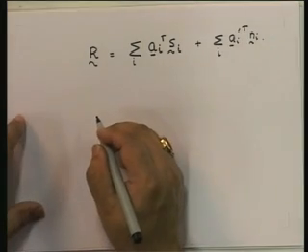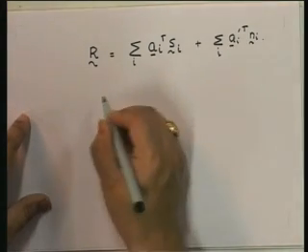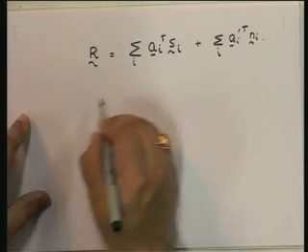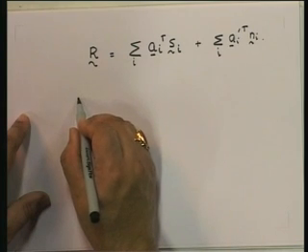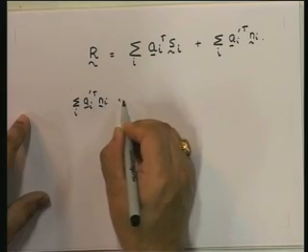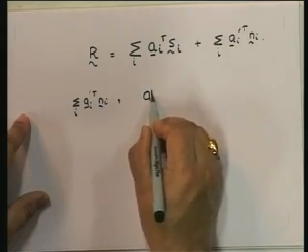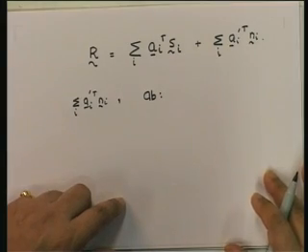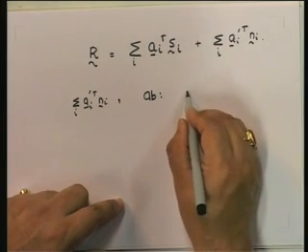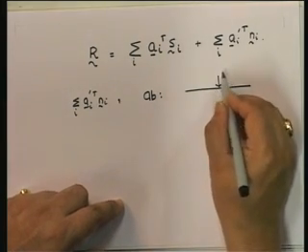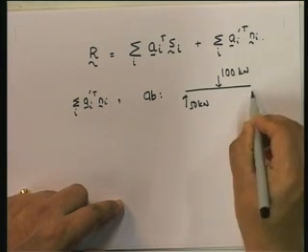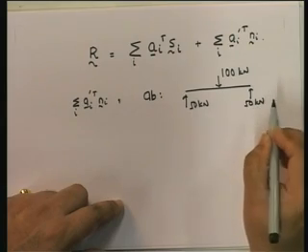If we put that in, this will only exist for the summation A_i into N_i, which in this particular case is only in AB, because that is the only member force that you have. The reactions for the 100 kilonewton are 50 and 50.